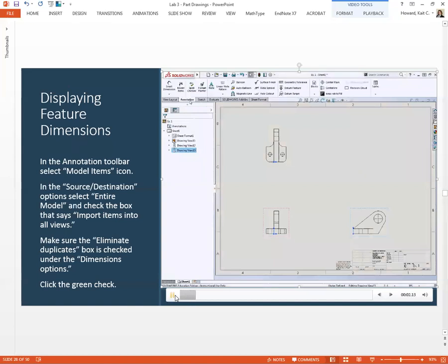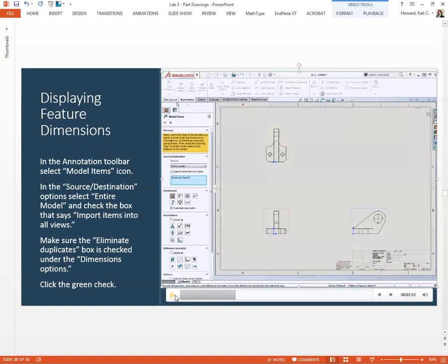So now we're going to create these dimensions. If you go to model items, you can automatically select to have the entire sheet dimensioned itself. Here is my caution to you. SolidWorks does an okay job at guessing, but you will probably be better off putting in each dimension one by one. So going back in and doing Smart Dimension one by one.